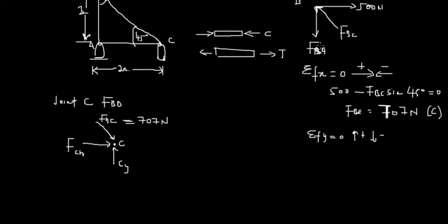So FBC is moving downwards, sorry, FBA, so most definitely it's negative. And then we have FBC. Whenever you move FBC towards the Y direction, it's always cos. Keep those things in mind. Whenever it's towards the Y direction, it's most definitely cos, and the X direction is most definitely sine. You can verify that from your SOHCAHTOA. Right, so let's proceed.